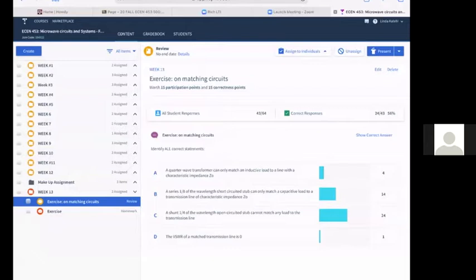Okay, and I was a little confused on this exercise, because a fourth wavelength open circuited stub, that's a parallel LC, but it can't be approximated as a parallel LC for filtering purposes, right? A shunt quarter of a wavelength open circuited stub, what does it become? Becomes a short. I remember in filtering, you cannot put a short someplace. It can become an open or a short, but it's a combination.